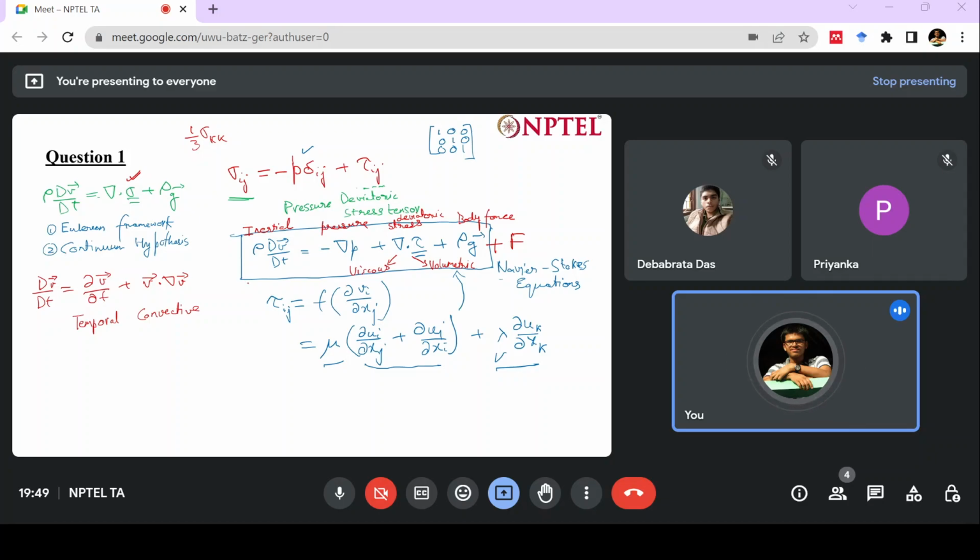And what is the convective term? The convective term is the effect due to the convection of my fluid. Combining these two constitutes my inertial term, the first term. And here are the force terms that we have discussed: the pressure term, the stresses, which include the viscous and the volumetric stresses, and the body force.